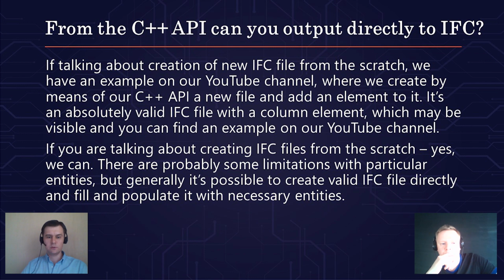It is an absolutely valid IFC file with a column element that may be visible, and you can find this example on our channel. If you are talking about creating new files from scratch, yes, we can. There probably may be some limitations with particular entities, but in general, it is possible to create a valid IFC file directly and populate it with the necessary entities.